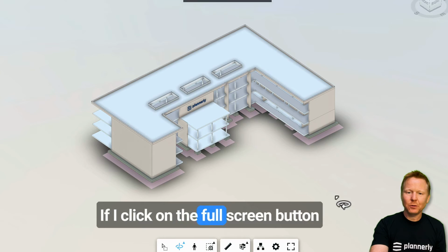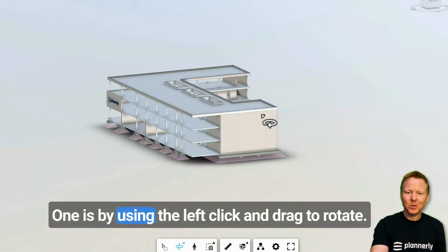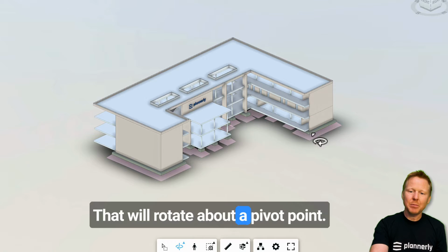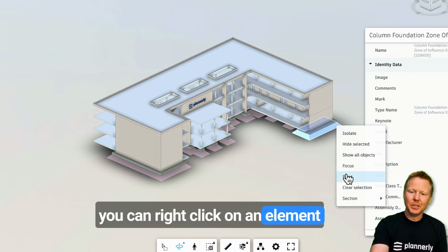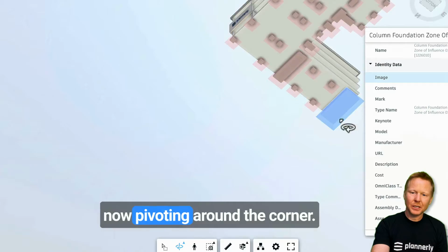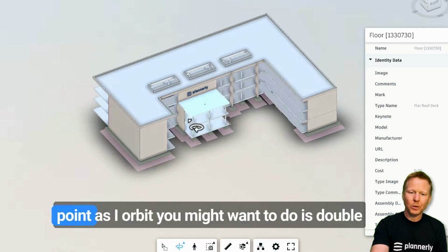If I click on the full screen button, we go to full screen of the 3D model. There are different ways that we can navigate. One is by using the left click and drag to rotate. That will rotate about a pivot point. If you are not pivoting about the point you want to, you can right click on an element and then choose to pivot around that point. So you can see how this is now pivoting around the corner, versus if I was to right click and then pivot around this object here. You can see there's a little orbit point as I orbit.